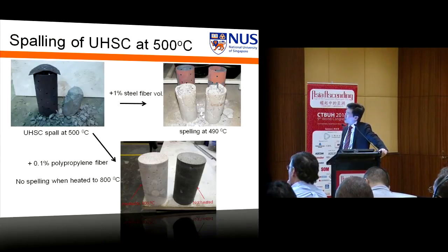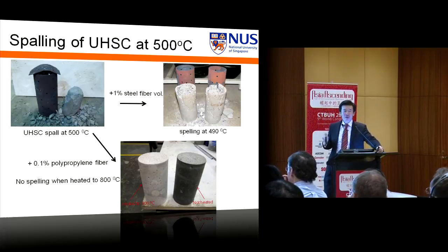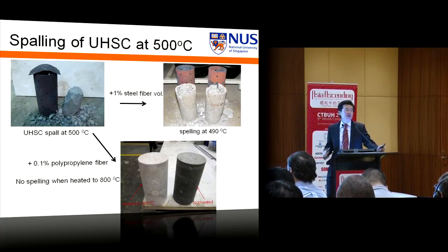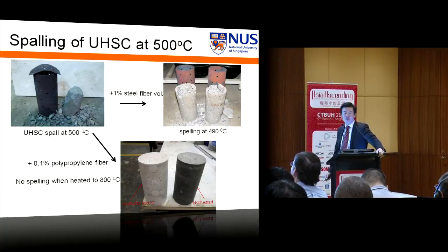Now, in the fire test, first we take out the ultra high strength concrete and we heat it up without any loading. You just heat it up. Suddenly, up to 500 degrees Celsius, the concrete again disappeared. Not only under axial force do you have a very brittle behavior, but when you raise the temperature, that means in fire situations, this concrete, without loading it, will also disappear. So a very, very violent type of behavior.